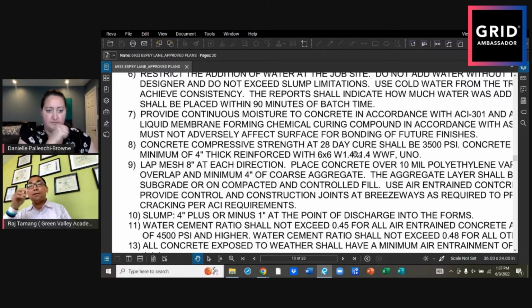The reason is that 3,500 psi concrete strength assumes you apply the full load on the structure. It means the house is ready, people are already in, your furniture, your kitchen, everything is fully loaded, right? But that's not happening, because you are only framing. That load is not there.